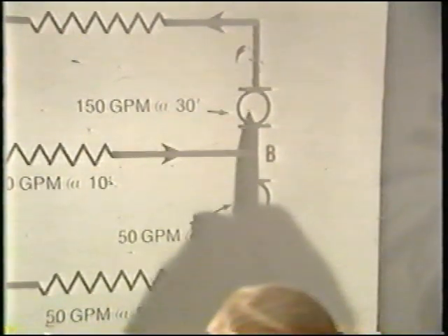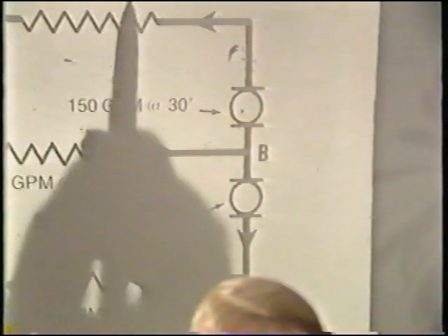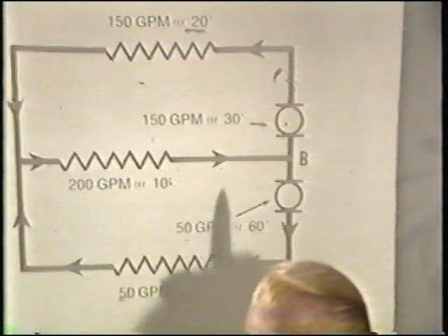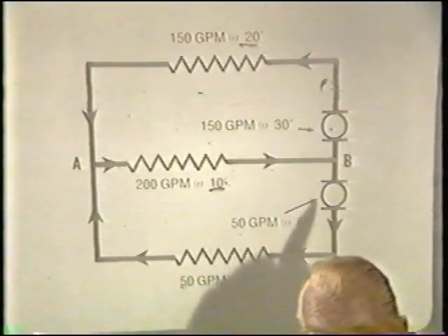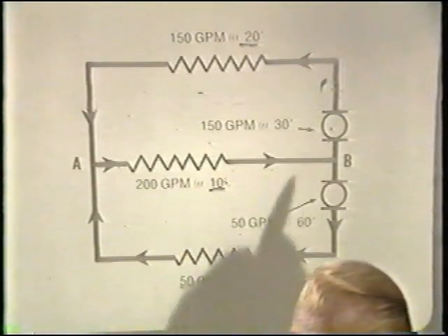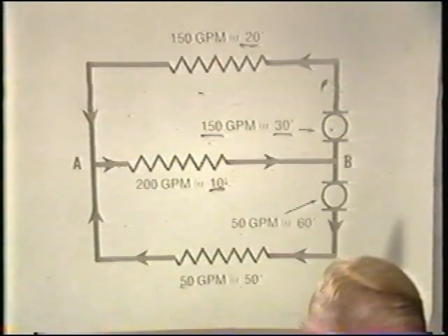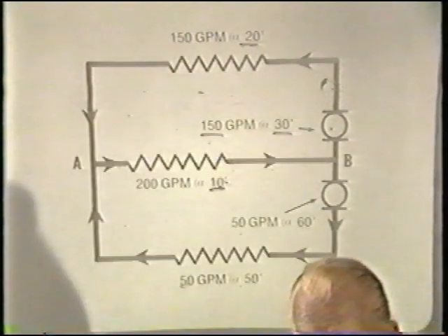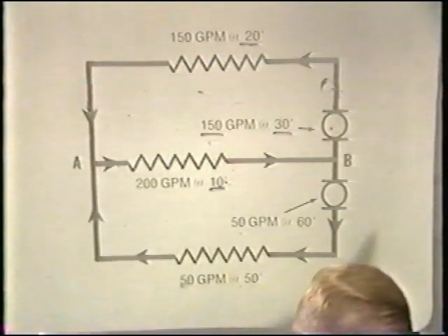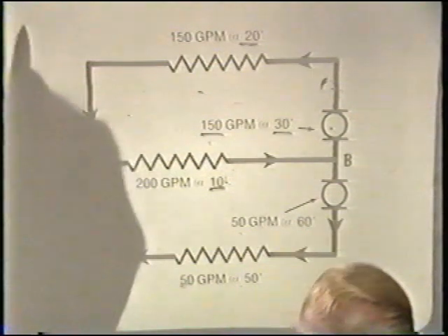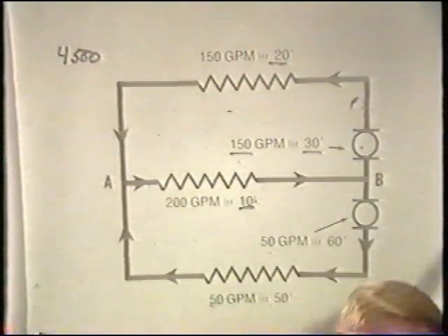The first pump would flow 150 gallons per minute at a 20-foot head loss through its circuit, but will require, in addition, 10 feet of head loss for that piping which is common to both circuits. So that pump will be 150 GPM at 30 feet of head. And we can establish a GPM flow head power draw for that of 150 times 30, or 4,500 GPM feet.